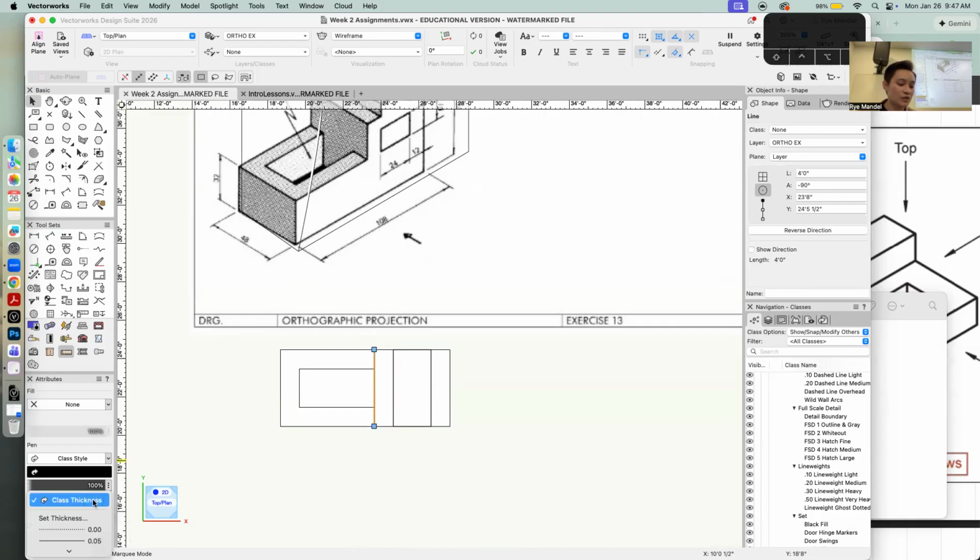You can also go into your attributes, and this is the non-class way of doing it, which is the way that I personally prefer for drafting. You can do it either way, it's fine. I like just selecting it like that, but it is a little less controllable, because this one has specific values like 35, 50, 25, 18, but a lot of times people just use point 1, 0.2, 0.3, 0.5, right? Those are the more normal ones you would have in a pen, which is why some people use classes over this, but I like using this because for me it's a little bit faster.